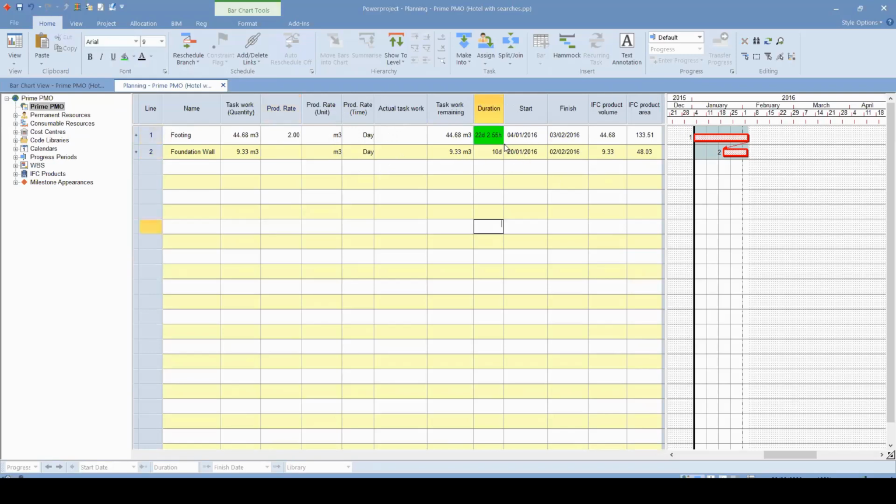I can directly see that the activity duration increased to 22 days and also some hours. That's why we know that we need to increase our production rates to 5, for instance. Therefore, we can finish this activity in 7 days.